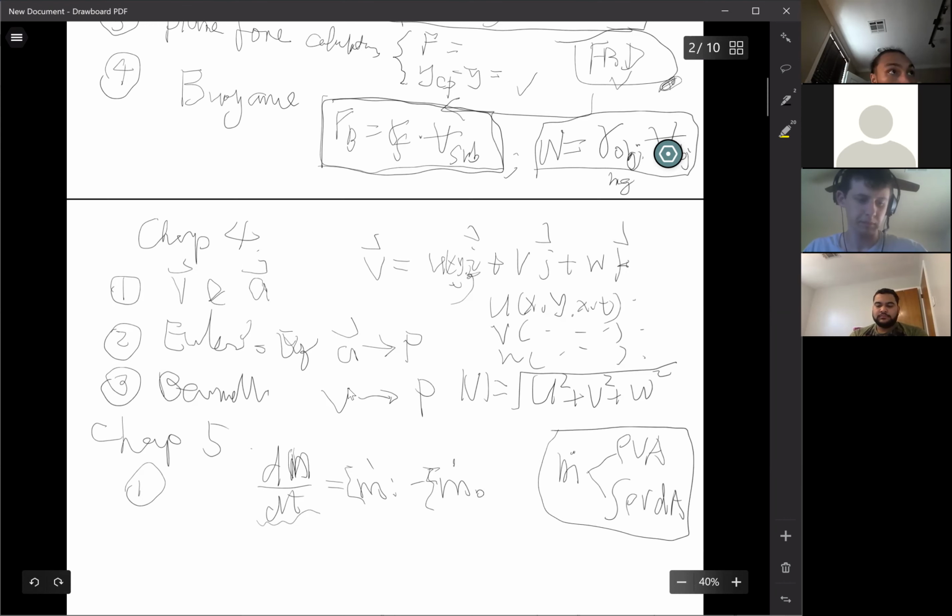Keep in mind the 2 ways to calculate the flow rates. One is if the velocity is uniform, which is easy. But if the velocity is non-uniform, you need to do the integration. That's a decision you need to make before you calculate flow rates. You need a flow rate for many problems, not only the conservation of mass problem, but also momentum and energy problems.